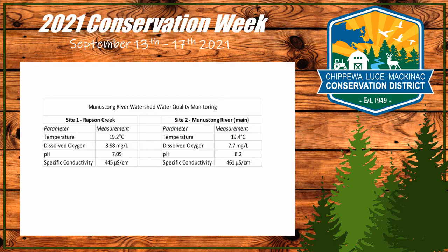Something else to note is at site 2, there was a lot of runoff occurring, lots of debris in the water, muck, we can say. The more organic material in the system, typically we'll see lower DO, because when bacteria decompose that material, it uses up dissolved oxygen, and that will lower the DO in the system.